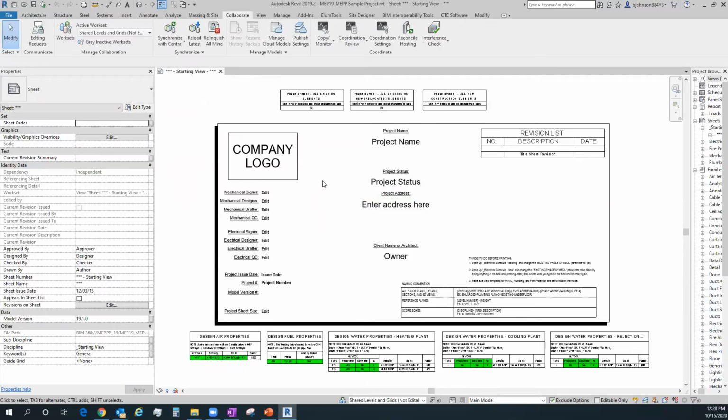So if somebody started an architectural model with room bounding lines and no actual walls, and they had those because they're 2D objects, they only show up on the view that they're created on, right? So then you have to know which view that is that you've done all your setup on and go back in and remove all those bounding lines for your rooms, because maybe you wanted to place room objects and get an idea of how big they were and run a schedule and know your spaces and do a lot of figuring ahead of time before you really start drawing anything.